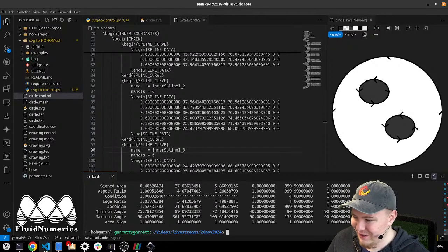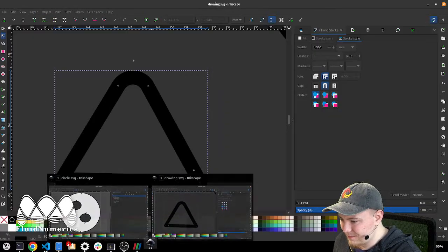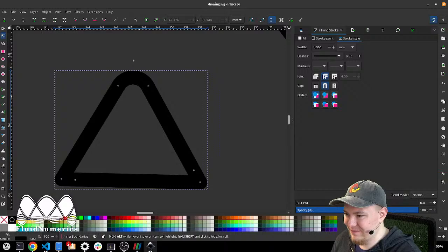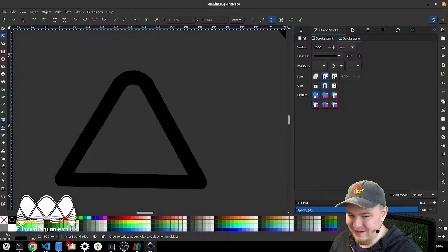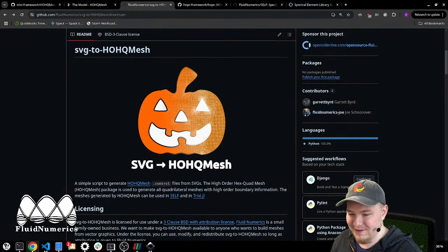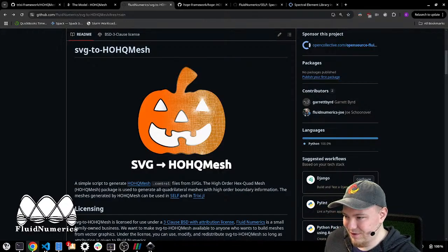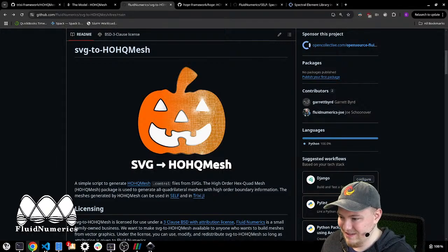Okay, we actually got a negative Jacobian, which illustrates my point here. I could spend more time tweaking this, but one thing to keep in mind is that rounded edges maybe do not behave quite as well as nice sharp edges. So to bring it back around with our jack-o'-lantern, we ended up going from these soft rounded eyes to these sharp eyes because it handles it better.